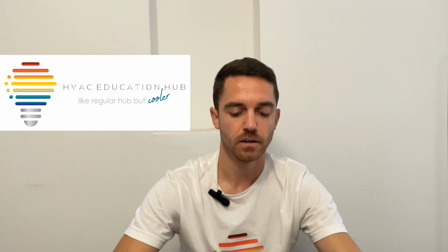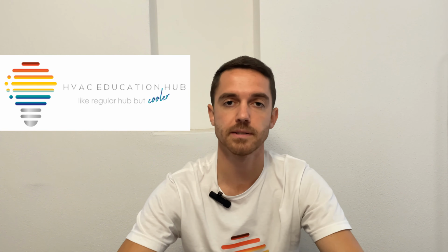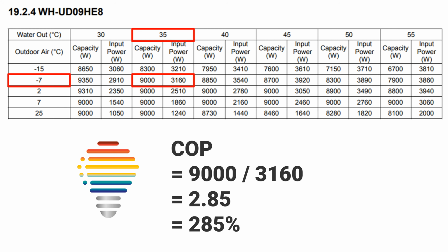Also, regarding outdoor temperature, we can see that when the outdoor temperature is dropping, our coefficient of performance is dropping because we have a higher difference. So for example, for 35 degrees flow temperature and -7 outdoor, our input power is not 1.86, it is 3.16, for the same heating capacity delivered, so 9 kilowatt, and our COP is 2.85. It means that it is lower than with a higher outdoor temperature.